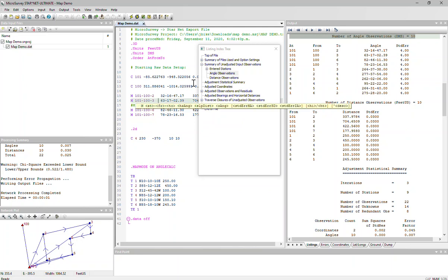And like I said, there's multiple ways of inputting those field measurements. They could be just regular traverse information. They could be weighted coordinates. If you had GPS vectors, you could have ties to the evidence that you have found on the ground.